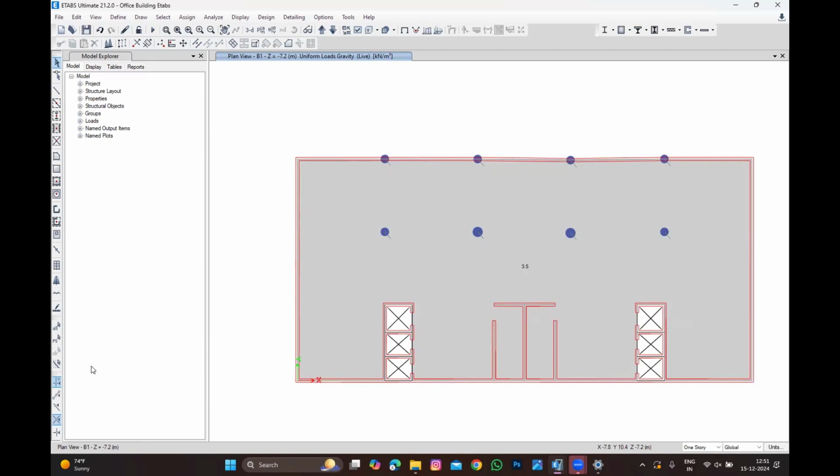Don't do undo. If you do undo, whatever commands you used previously will all go, even the application of load will go. How many times you do undo, that many times it will go. Sometimes the redo will not come, because where you saved the undo, like 3 options before, it will stop there. Then further 3, 4 commands, you will not get it.